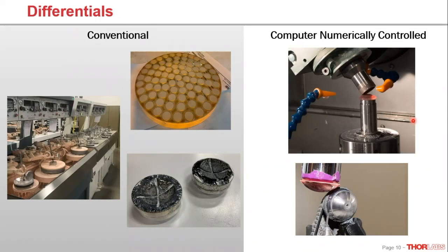Another driver of available lens types is how they are produced. Lenses turn up throughout ancient history, but the practice of grinding and polishing really emerges in the late 13th century. Progress through the centuries brings us to the techniques for producing lenses and plano optics known today as conventional fabrication. The methods employed lend themselves to large tools of uniform spherical surfaces, leading to the ability to batch several pieces to a block and produce low surface error parts.